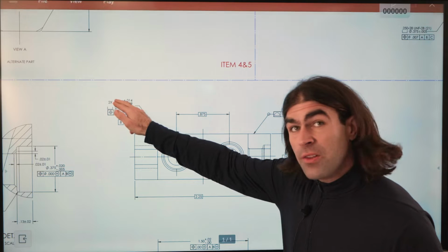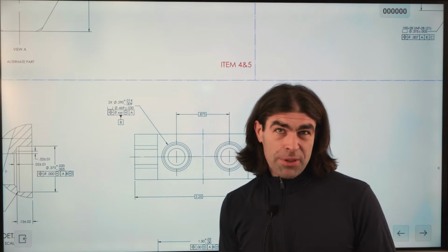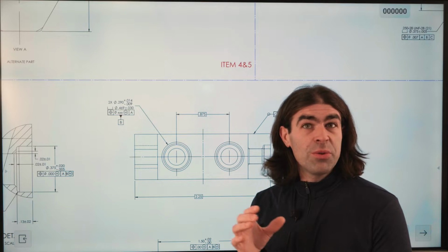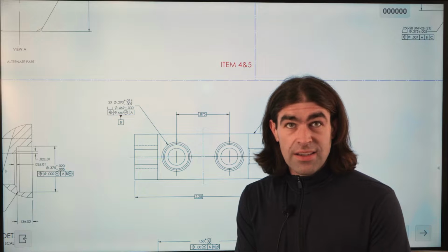So we're just going to look at our clearance hole right here. The counterbore we're not going to worry about. Typically, if you have two diameters mating to two diameters, only one set needs to locate.